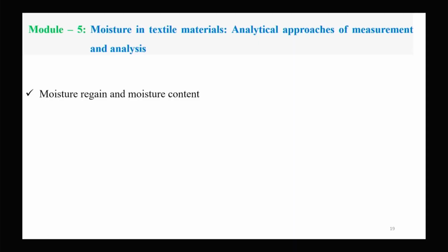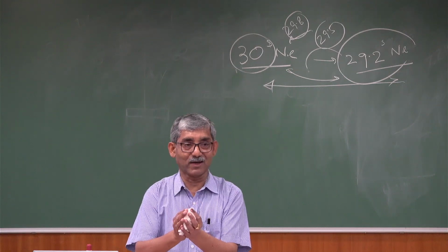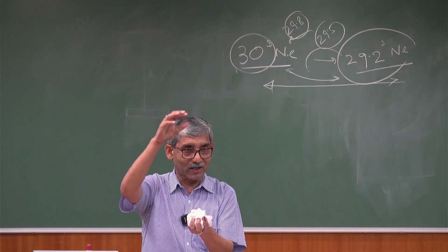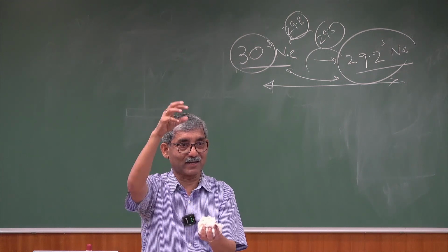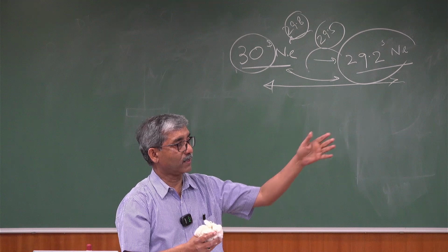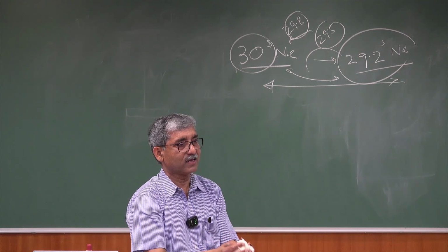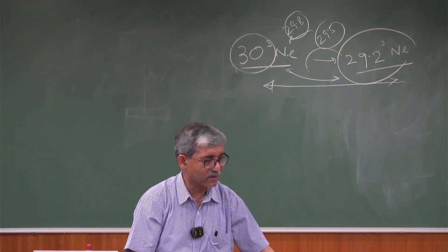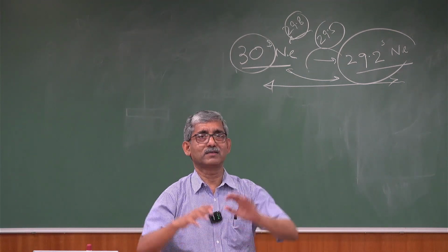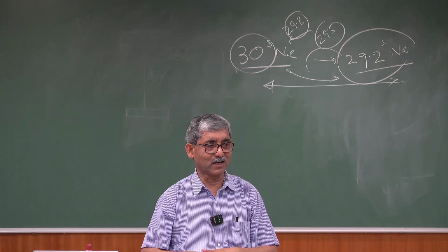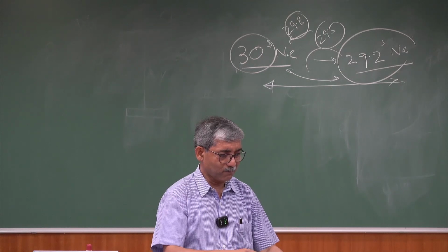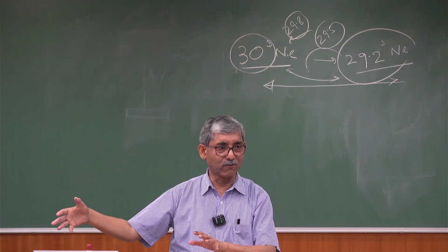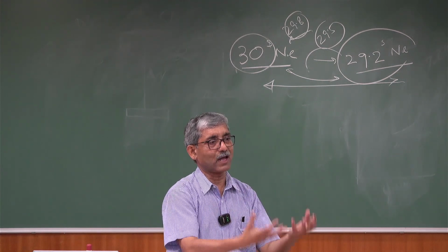Regain means what? You have a completely dry material, then how much moisture is it taking? I am drying it completely, so no moisture is there. Now I am putting it in this room where, say, 65% relative humidity is there, and after keeping it for a certain time, say a full day, it keeps on absorbing moisture.